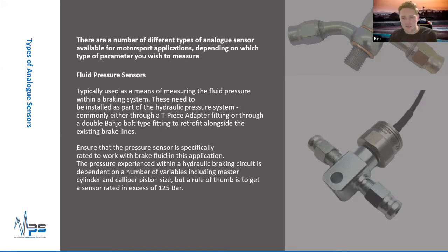I really would advise, if you can afford to build it in as part of your brake monitoring, to use a brake fluid pressure sensor. Just a few things of note. The hydraulic brake fluid can be corrosive to some types of sensors, so you have to make sure you buy one that's specifically approved for use with brake fluid. And you can see really high, or comparatively high, peak pressures in the braking system. So you want to make sure you've bought a sensor which is designed for that.